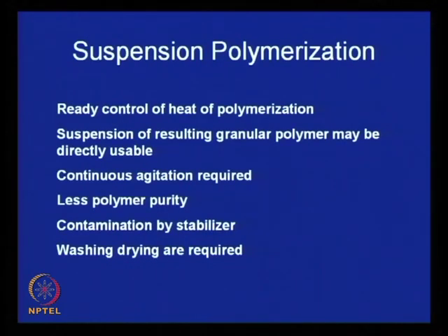Here you see these are the characteristics shown. Ready control of heat of polymerization, as I have already said. Suspension of resulting granular polymer may be directly usable. That means sometimes the suspension can be used directly, or if it is filtered, we can get particles isolated, washed and dried. Continuous agitation is required, there is less polymer purity, and contamination by stabilizer, washing, drying, etc. are required.